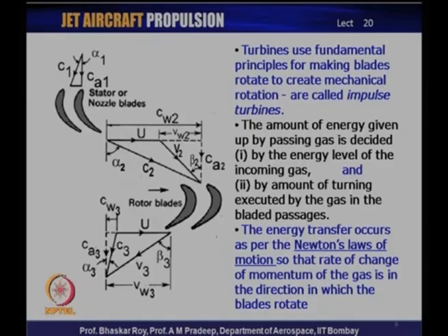That is what creates the reaction. In aircraft gas turbines, typically the exit Mach number from the stator nozzle, M2, corresponding to C2, is pretty close to 1. Indeed, it is deliberately made pretty close to 1, which means the flow coming out of the stator nozzle has gone sonic. In gas dynamics, you would say that the stator nozzle has gone choking.